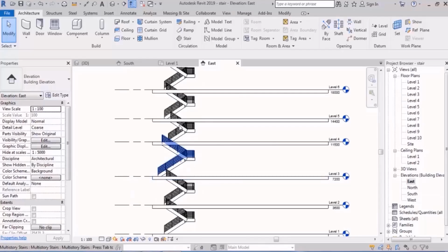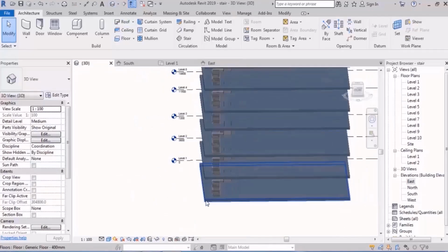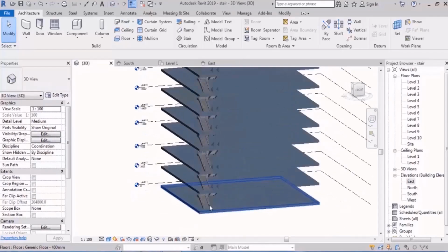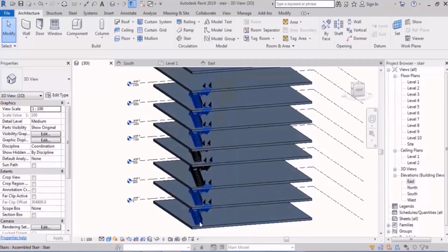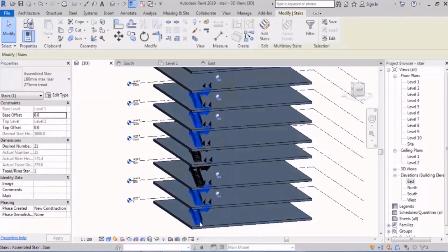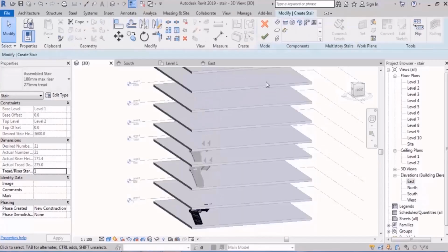But it's interesting that while you're doing this and then you tap on one of the staircases, those two will not be selected. But why? Because those two don't have the same height anymore. And definitely they can't work with the rest of the staircases anymore. Even if I click on the edit, you see we can't change them. Only the ones similar to each other.